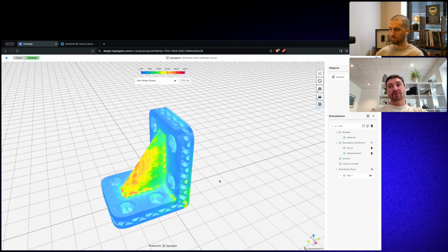Of course, there are rules of thumb that we automatically employ because you can technically decouple the two. For example, if you have a given wall thickness, you want to have a specified number of simulation elements inside that wall in order to achieve convergence for your simulation. So, of course, that is an important part.